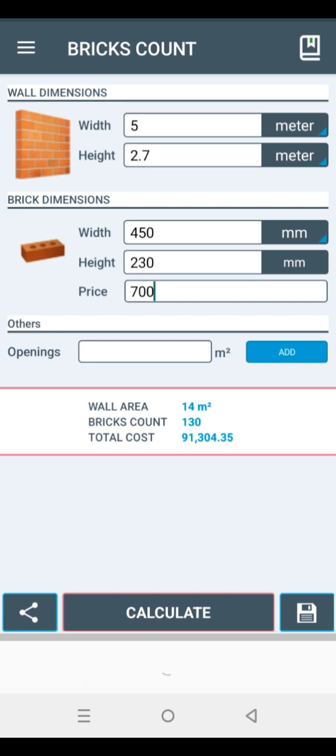Although we always calculate that for 1 meter square of block work, we are going to have 10 blocks, it reduces to about 9 point something, so let's just leave it. If I'm to do this work, I'm going to request at least 140 blocks. Probably I will request 140 to 150 in case there is any breakage. You understand what I mean? So I just request 140 to 150. So let's say I'm done with the block count.